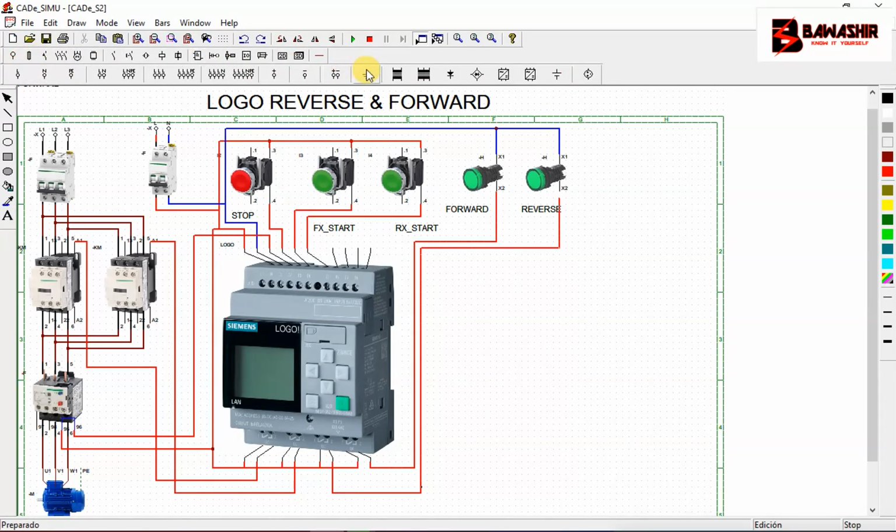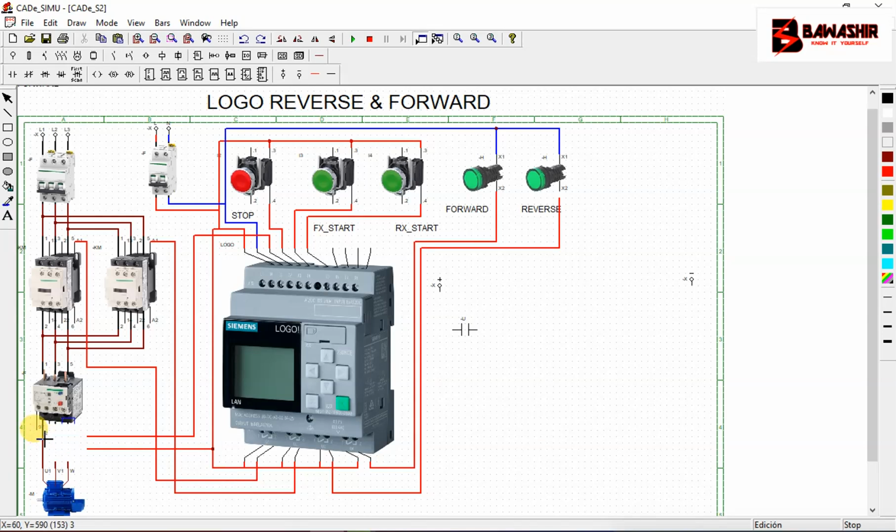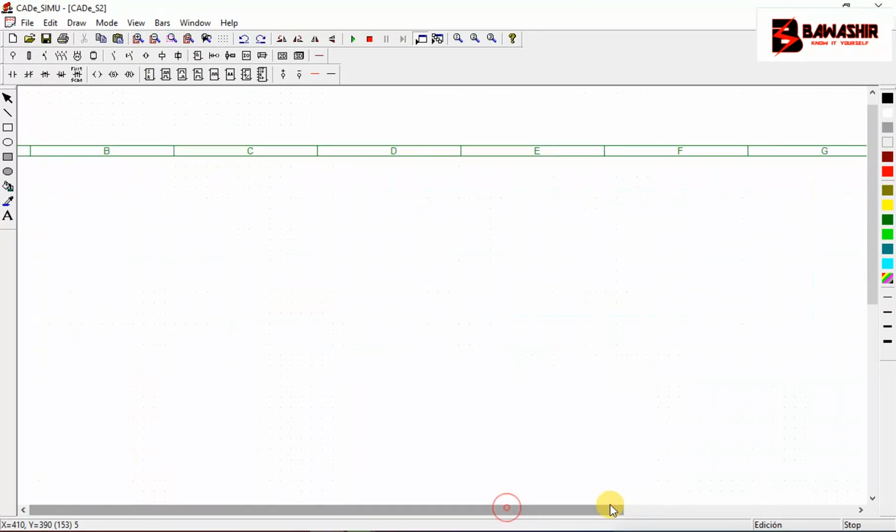I'm going to come here and have a positive, and come here and have a minus. I'm going to have our ladder logic programming. Now normally open, we are going to start. This normally open is for the overload, because we passed in the normally closed of the overload, so we use here normally open. That means when we power this one, it will have to do what? To close. But had we passed in the normally open of the overload, then in the ladder logic it would be normally closed. Are we there? Let me zoom a bit our program.